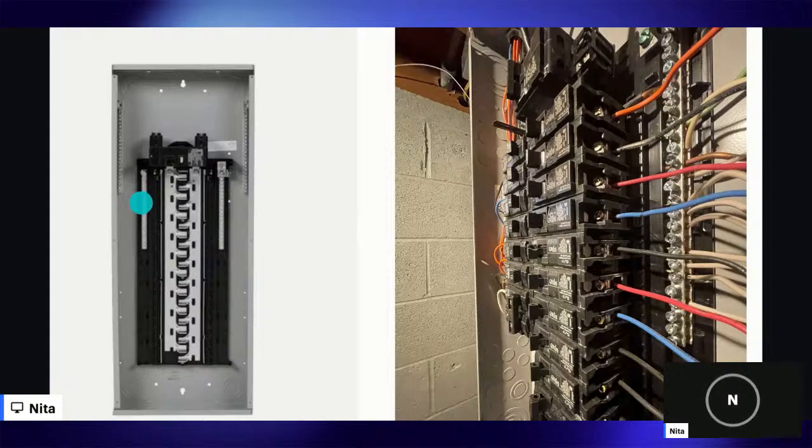We're going to talk here in a minute about our grounding system, which is basically the safety system, because again, the electricity is constantly flowing and it's looking for any sort of conductive material to jump onto, and we don't want that. We only want it traveling on the appropriate circuit. But in the case of a fault, we need a safe path to clear that fault. That is where our grounding system, our ground wire, ground bus, comes into play.